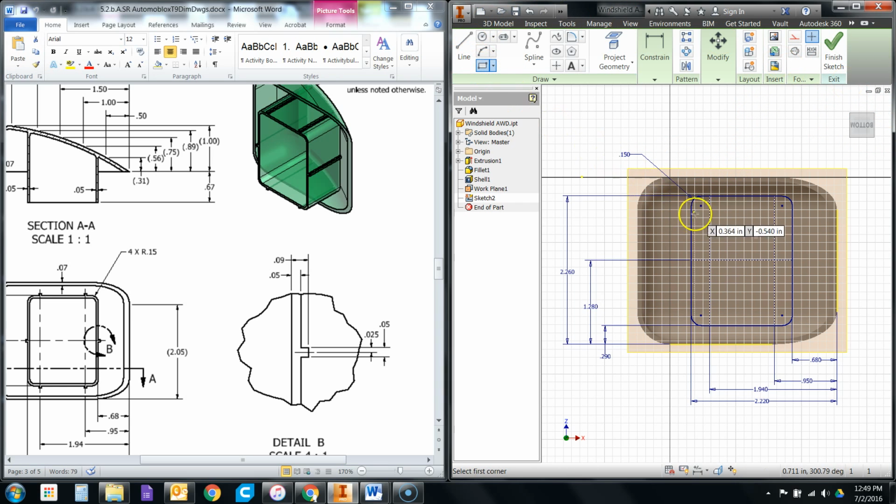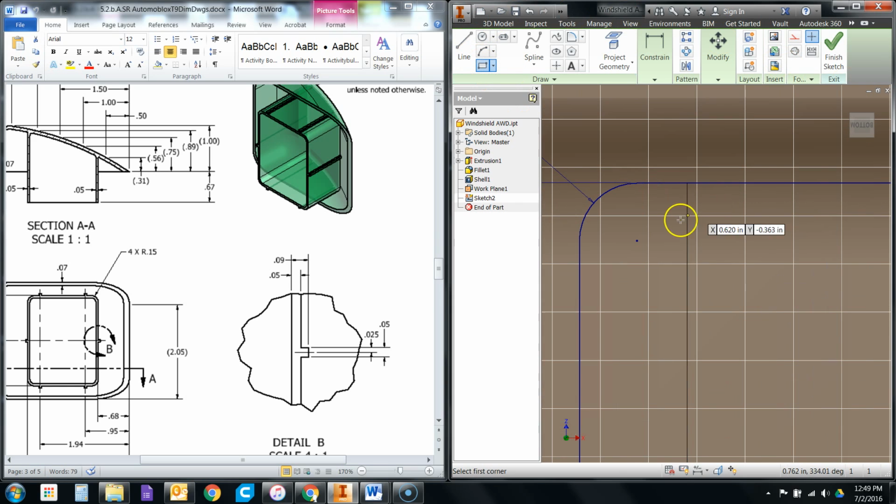I'm going to go ahead and apply these little rectangles, and that's what these things are for. They represent the center, you'll notice here in the detail view, the center of these little rails or knobs that stick out. So this is detail B, and it shows me this knob and this center line running through it. And I can assume, since they're not giving me any other dimensions for the other rails, that they are all the same. So here's the center line, and it says, all right, the entire knob in its, let's reference this